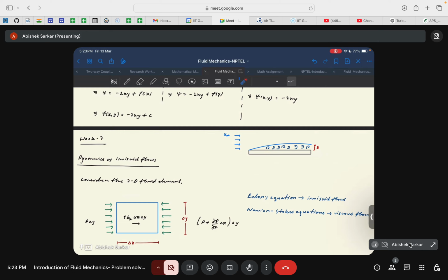The upper layers of the fluid will try to drag the lower layers of the fluid, in a way that it tries to accelerate the lower layers, which will in general create the well-known velocity profile that we know, which is parabolic in nature. So the effect of the plate is propagated to the higher layers of fluid, which feel the presence of the plate by virtue of viscosity and the velocity gradients, of course. Or you can simply say, because of the shear stress.